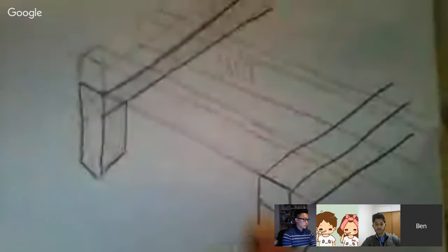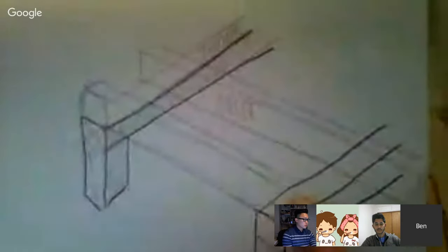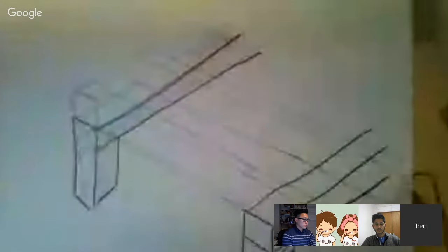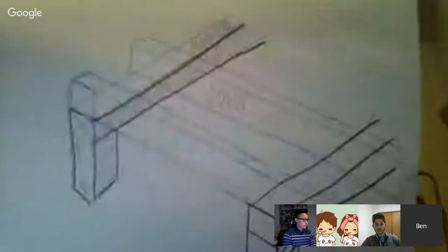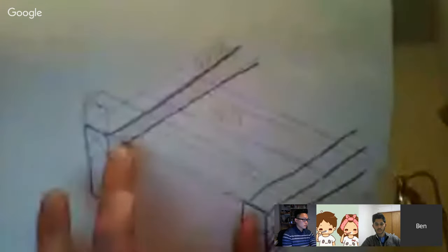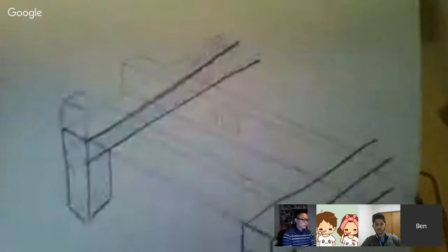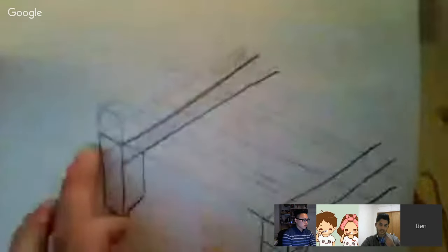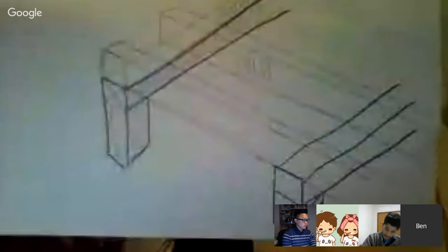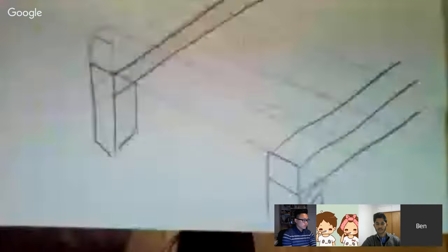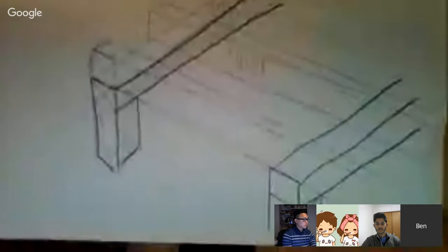Yeah, so those members, the piles and the bearers, run in the same line as the piles. And then for the joist across here, your loaded dimension, the span is the distance between the two bearers. Does everyone understand that? So what the joist is sitting on is those two bearers, but the line of the bearer is also the line of the piles which hold the bearers. Has everyone got that? Do you understand that? The person who asked that question about the loaded dimension, how that sits?